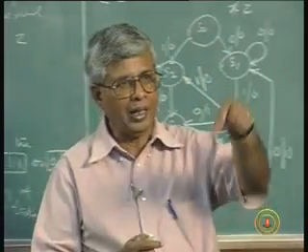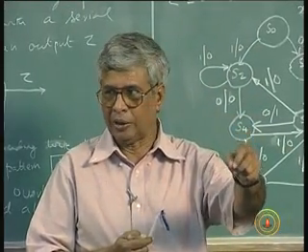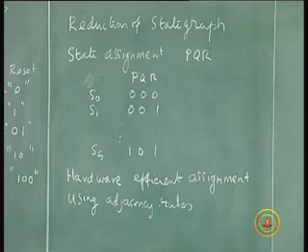I had to buy and put an IC. One AND gate meant one extra thing I had to put. One multiplexer, one extra thing. One flip flop, an extra one. For each one I had to go and buy an IC and put it there. It takes more space, more power, more money, more everything. Speed is reduced. So in those days hardware reduction was very significant.